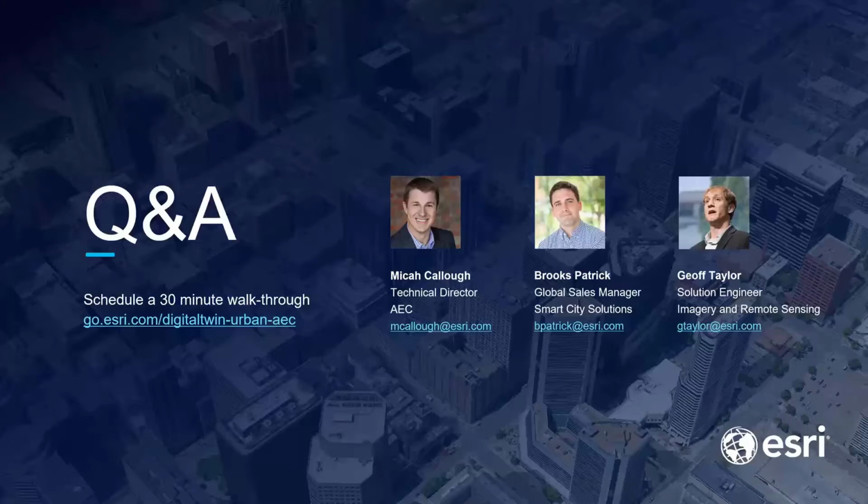Beyond that, when you're starting to work with your city, county, or town, or just an urban area, the 3D base map solution and the LiDAR classification tools support anywhere from sub 1 meter, probably like 2.5 feet or less in the point spacing, is really where you want to have your density of your LiDAR. And those work very well in classifying that point cloud.